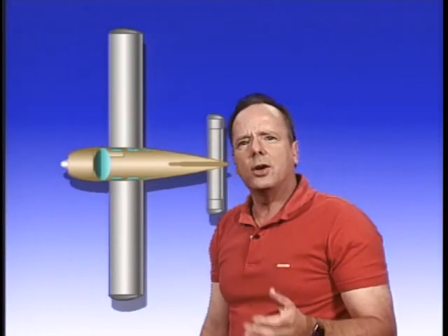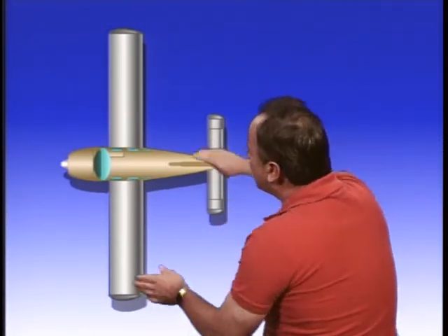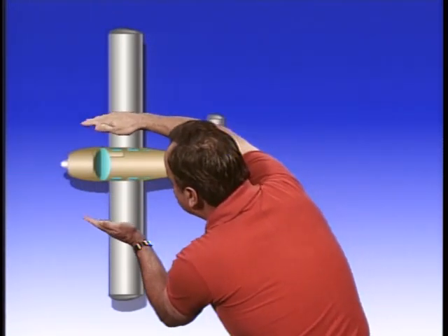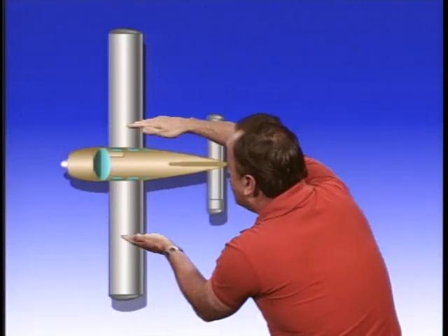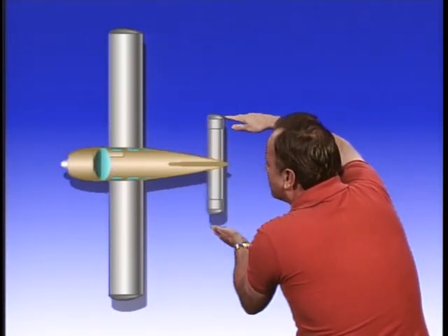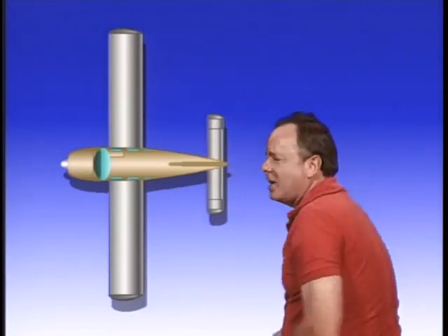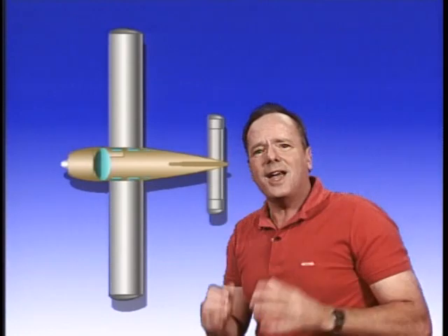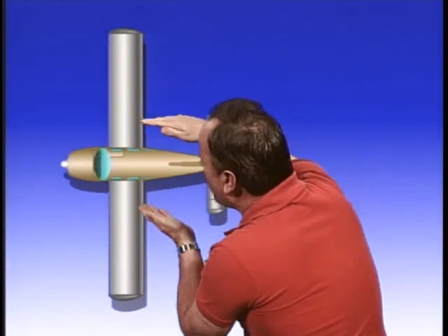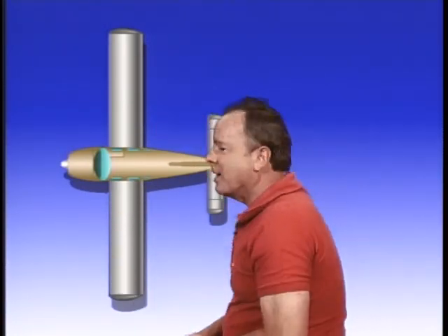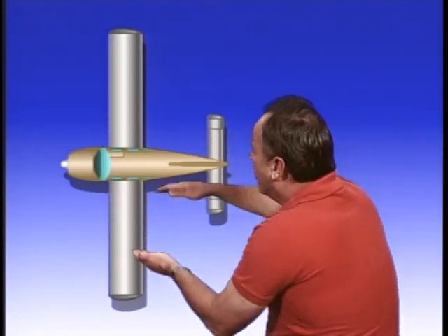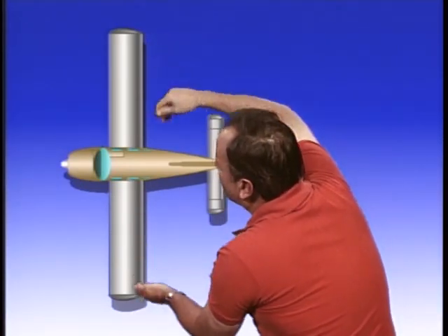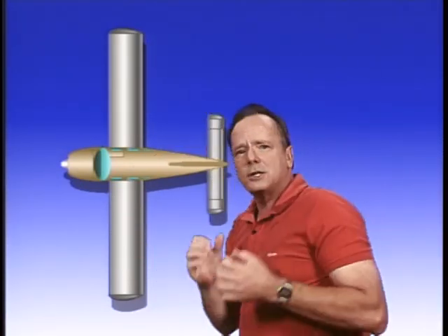and that is a very, very good thing, because what happens is you still retain aileron control out here because you're not stalling at the tips, you're stalling at the root first. And at the same time, when the wing stalls at the root first, you now have a lot of aerodynamic warning of the stall, because this disturbed air comes back here and hits the tail and then shakes the wheel of the aircraft, and therefore it wakes the pilot up and says, "Hey, this wing is about to stall." So a rectangular wing is a very good wing for low-time pilots, because it, one, gives you very good stall warning to let you know it's about to stall, and number two, gives you control throughout the stall right up to the last part of the stall.